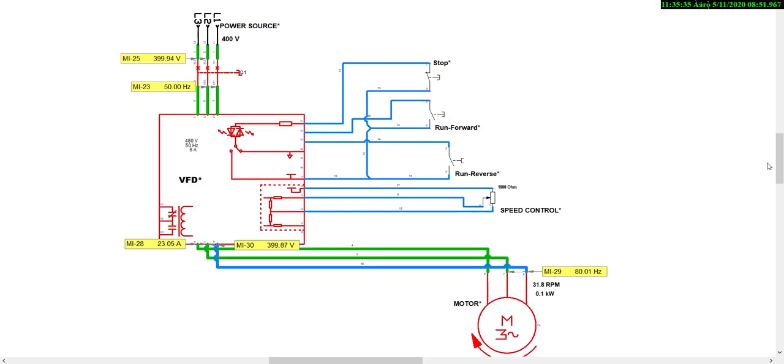So I will send a forward signal to our VFD. You can see our electric motor is gradually gaining its speed because VFD also works as a soft starter. When you look at our current output here, we have 22.3 ampere output, and it's gradually reducing. Although the reduction is not much, you can see that this is better than 3 or 4 times the starting current that we use in contactor control.